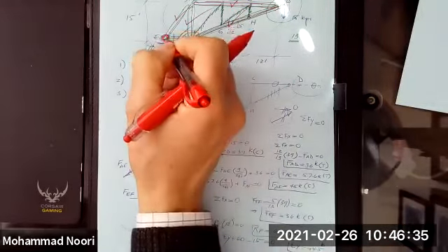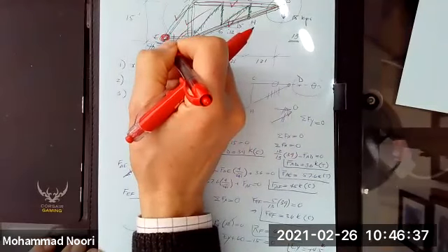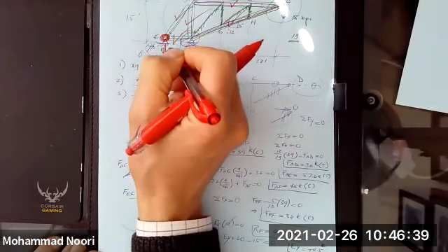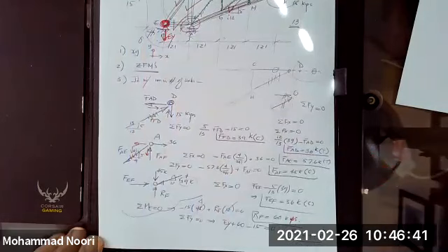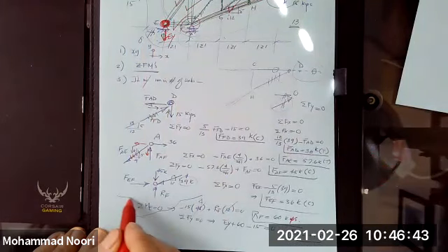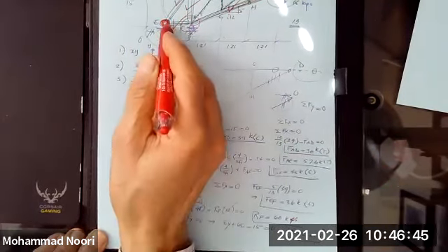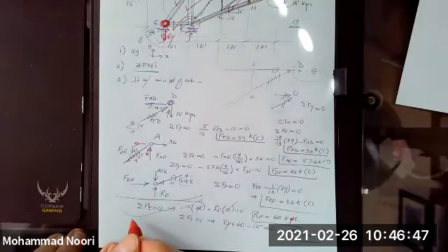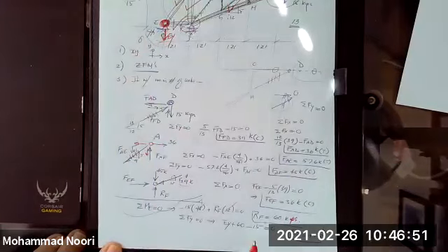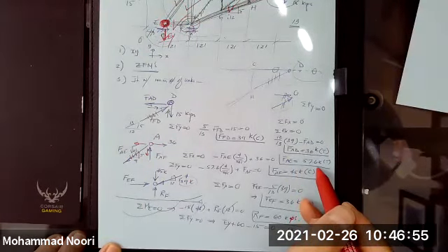So I have these two unknowns. Let me use this joint to confirm the answers that I have got were correct. So let's use this free body diagram. Force of AE, which we had found here, is 57.6 tension.